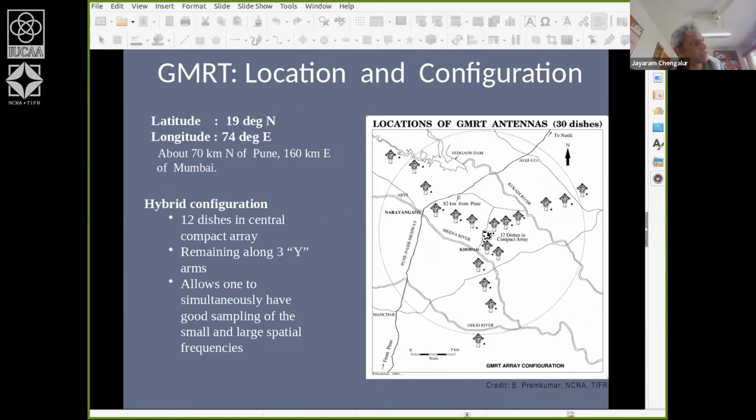There's an inverse relationship between the wavelength on the sky and the separation on the Earth. So we spoke about this being like a filter, right? If I have antennas which are very far away, they're only going to pick up high frequency oscillations in the sky, but oscillations in space, not in time. So basically it picks up fine scale structure on the sky. If the antennas are close by, they will filter out all the fine scale oscillations and they will see only the sort of large scale structure of the source.